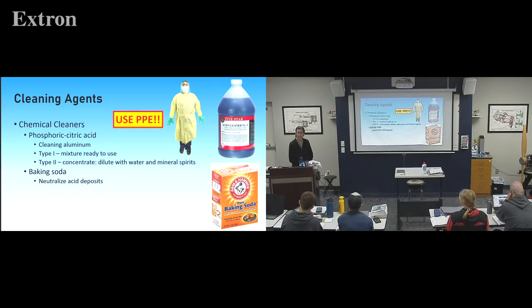If you use baking soda to neutralize, so that spills some battery acid on me, right? Would I wash with water first? Would we sprinkle it on the arm? Would we make like a little paste first? What's the best? Rinse it all off first, then paste, smear it on, grab the SDS, see what else it says.